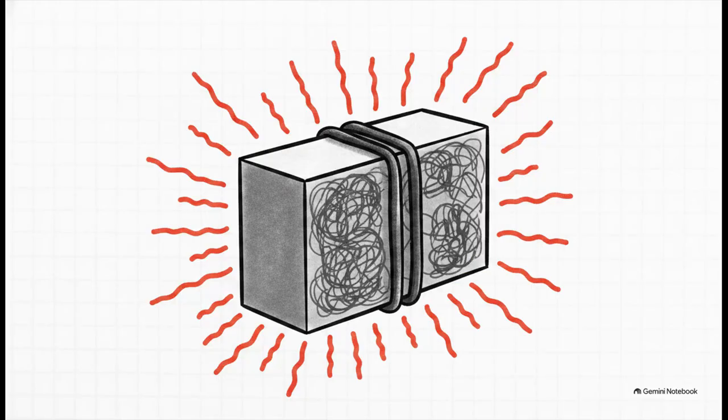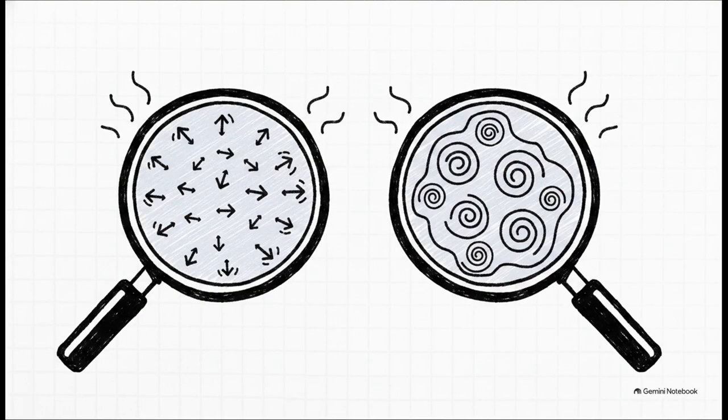Okay, let's face the realities of engineering for a second, because unfortunately our magnetic plumbing is not perfectly frictionless. Channeling alternating magnetic flux actually comes with a cost. We call these core losses, and it's essentially energy that just gets wasted as heat inside the ferromagnetic core. These core losses basically come in two flavors. First up, hysteresis loss. Because we're using alternating current, the magnetic domains in the metal are constantly flipping back and forth, and they actually lag behind the magnetizing force. This magnetic friction creates heat. Engineers fight this by using specialized silicon steel, which is just a brilliant material science solution.